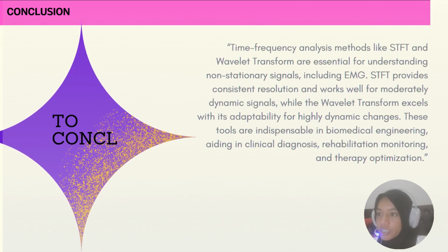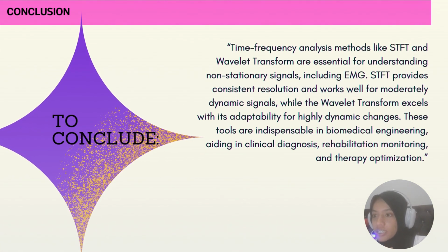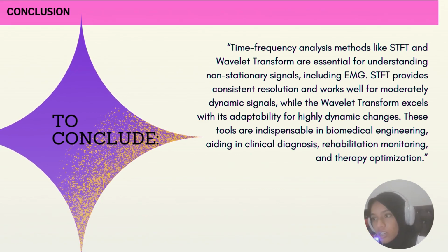To summarize, our analysis emphasizes the importance of the short-time Fourier transform and wavelet transform in processing EMG signals. While the STFT provides consistent resolution for moderate signal variation, the wavelet transform adapts well to higher dynamic changes. Both methods play a role in biomedical engineering to support diagnosis, rehabilitation, and therapy.